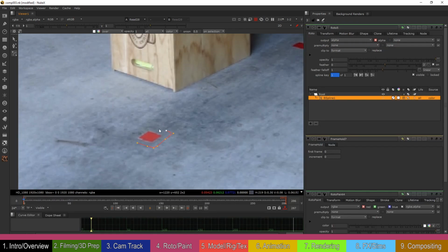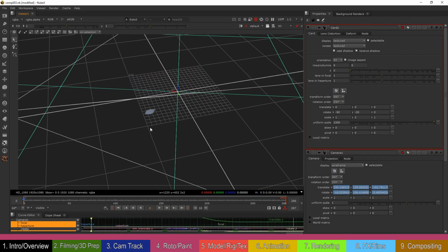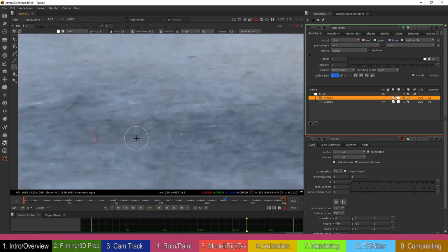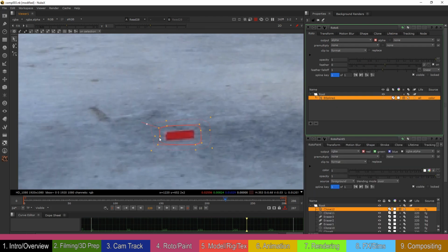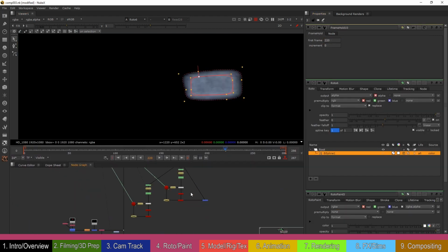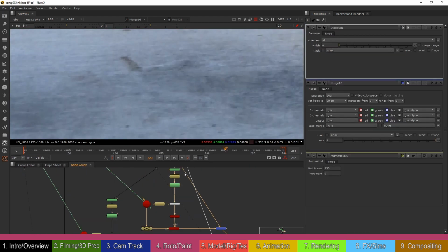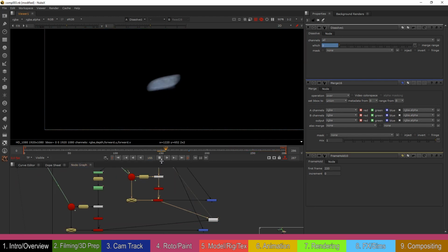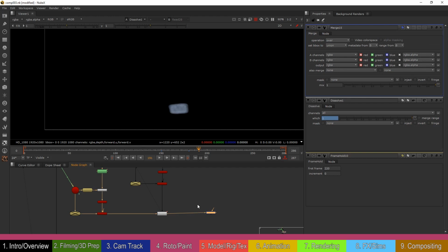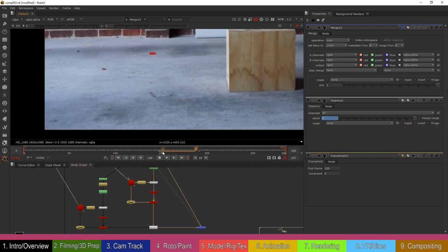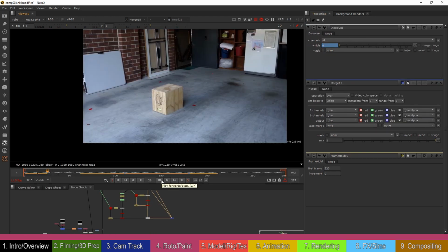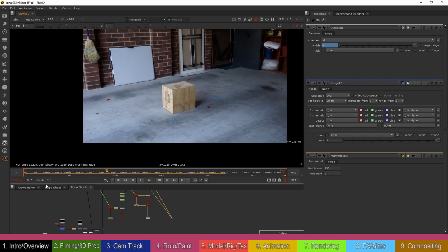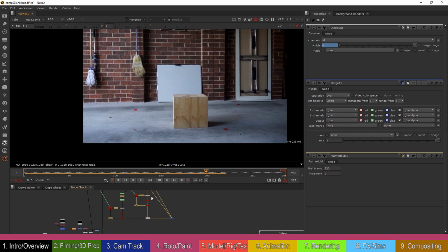I'm using the 3D camera track to project my clean patches right on top of the red markers. This meant I only needed to paint 2 patches for each marker to cover it up. One was at frame 0 and another one was at frame 220. And all I'm doing is a nice slow dissolve between those 2 patches over the course of 70 frames to manage any changes in perspective and lighting. Due to parallax and perspective change, doing all of this without a 3D camera would have been extremely difficult. At the very least, all those small transformations and warps would have been super time consuming.